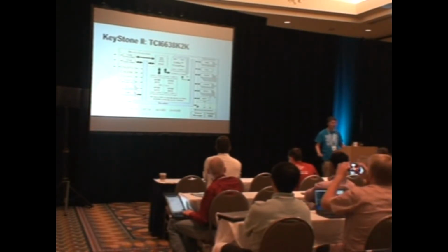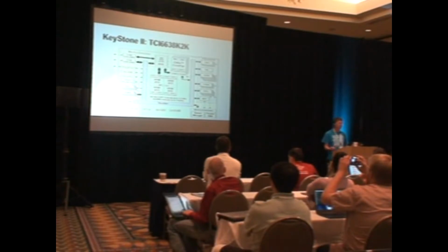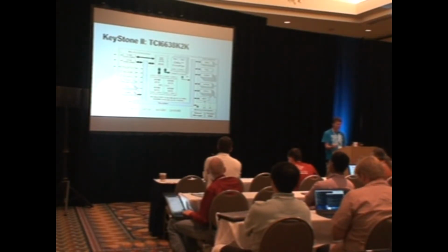So we get parallelism by having multi-core machines of the same architecture. Here we have a multi-core machine. I mean, technically each of these accelerators counts as a core, but it's a core that only does one thing. So it's basically an ASIC. The DSPs are cores that are good at particular forms of algorithms, and we have 4 cores of general purpose processing. So these are all good at doing different things.